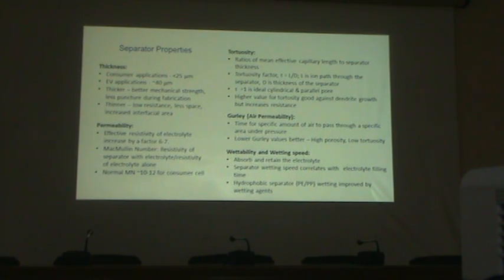Why is it detrimental? Because we are talking about our electrolyte LiPF6, which is going to be attacked by any amount of water in it. Yeah, immediately creating hydrofluoric acid. Corrosive, your cycle stability will fall down like seconds, like 10 cycles, it's gone. So that is why water content is very important. That's why this is kind of a help for us. At least on the anode side and the separator we don't worry about. We worry only about the cathode and the electrolyte. So if you maintain good standards in that, then you can get over.